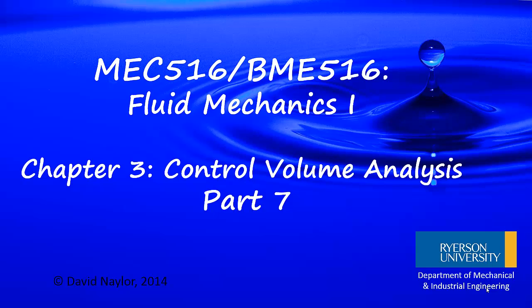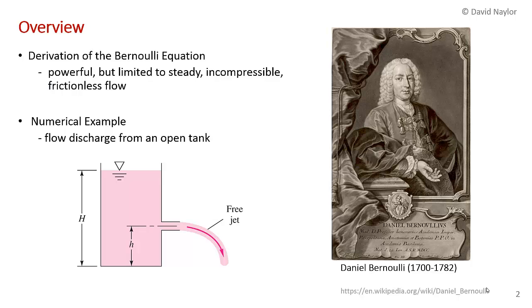Okay, this is Chapter 3, Control Volume Analysis, Part 7. In this video, I'm going to do the derivation of the famous Bernoulli equation. As you will see, Bernoulli equation is a powerful tool in fluid dynamics, but it's limited to steady, incompressible, and frictionless flow. We'll talk more about the limitations as this video proceeds.